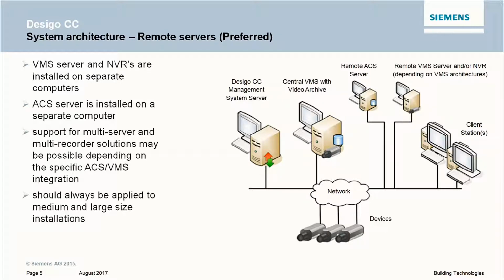We have seen this some days ago. We have updated an 8.1 Desigo CC with a video system on top. The smart one, we first updated the Desigo CC to 3.0. Then we have found out, it's 8.1. We need to update to Windows 10. So we updated Windows 10. Guess what happened? Video failed.